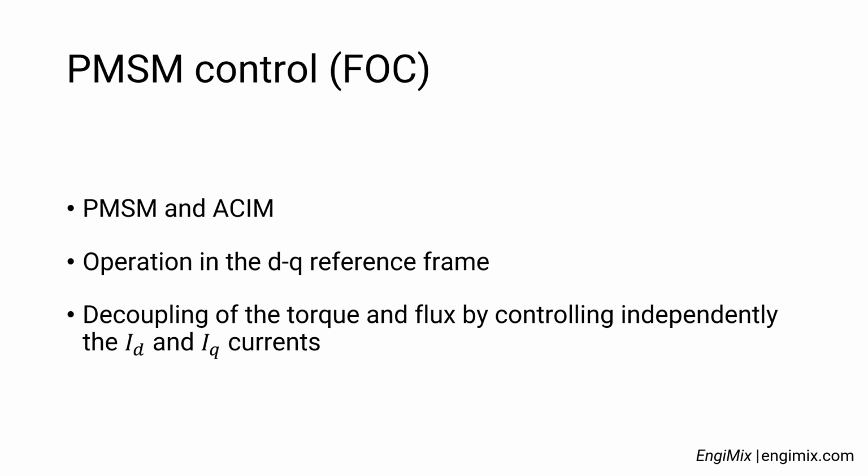With this method indeed, it is possible to control the torque and the flux independently by acting on the currents in the D and Q reference frame. This allows for precise and independent control of the motor's speed and torque, resulting in improved performance and efficiency.